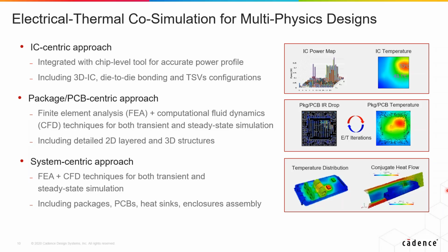From the software and simulation point of view, to my knowledge, there is no single software that can cover 10 orders of magnitude of physical size. In IC design tools, we have EDA or ECAD tools, and package and PCB is in between, where people use finite element analysis together with CFD. It could be a layered structure in 2D or a true 3D structure, trying to resolve thermal issues from an electrical, mechanical, and thermal interaction point of view.